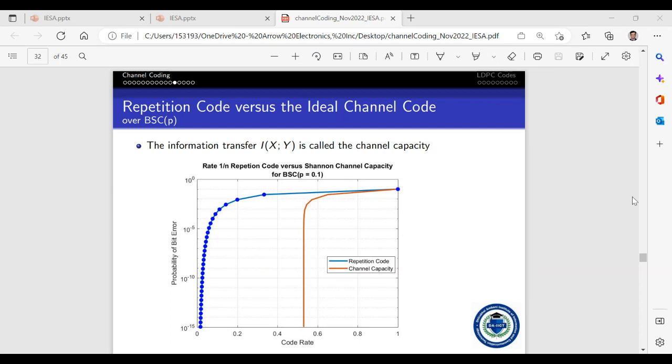You switch it off on an as-needed basis, so when there is nothing to transmit, you switch it off, or you switch it off in a deterministic manner, on a periodic basis. If you use, for example, a duty cycle of 1/3, well, maybe that is a little bit like a reverse of repeat-by-3 coding, right? 2/3 of the time you switch off the transmitter, you transmit only 1/3 of the time.